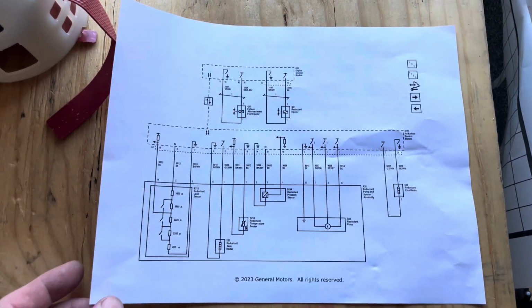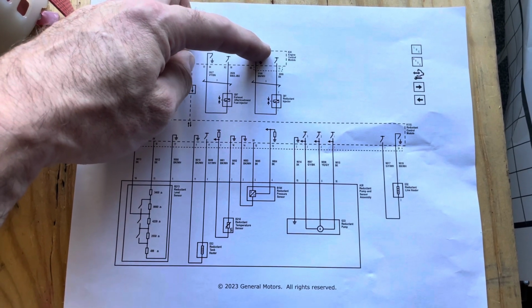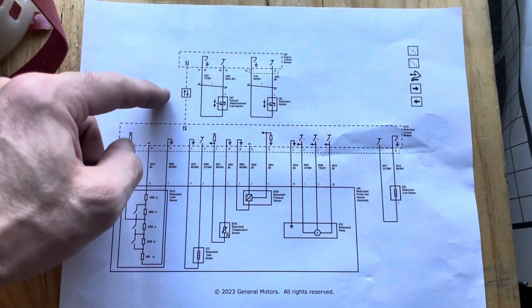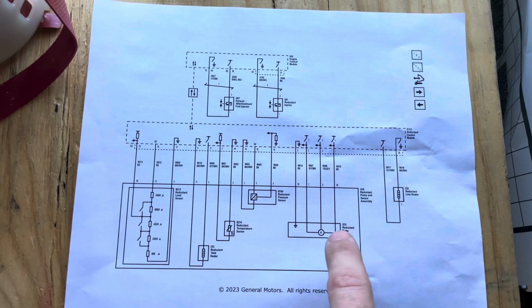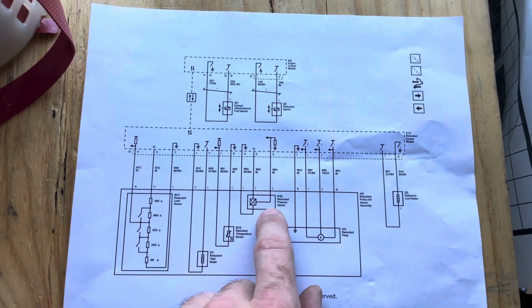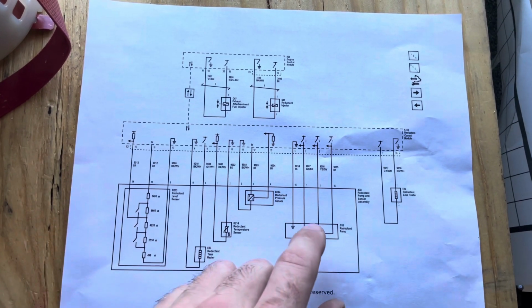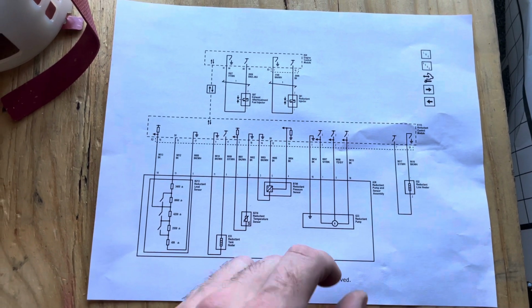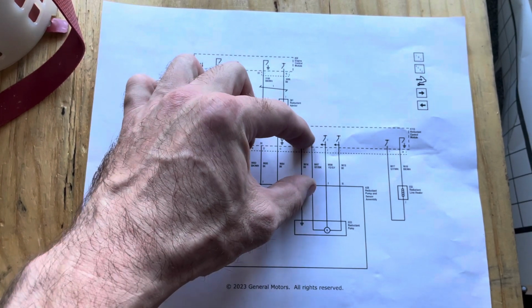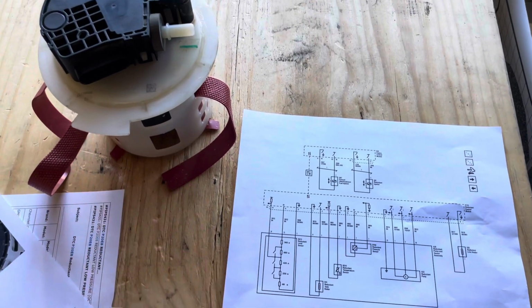You'll also notice that I did not do any electrical testing, and the reason for that is because the engine control module sets the code, but that data was communicated from the reductant control module, and the reductant control module is responsible for monitoring the pump and the pressure sensor, and it's all kind of self-diagnosing. So there's not really any external testing I can do, and the pump itself is a 12-volt 3-phase motor, so there's not a whole lot of circuit testing I can do other than, I can test from here and here, and that's about it. So I ended up just replacing the pump, and that took care of it.